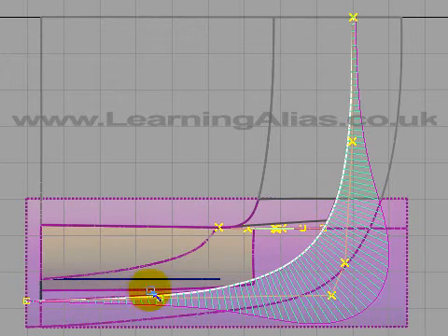And then when you've done that, obviously you have to bear in mind that this must run down the shoulder and be parallel to the side glass. So that's very important. You must set that up. You do that by attaching another curve here, shaping it to be sympathetic to the side glass, and then aligning this curve to that one. When you've done all that, you can project it. I've put the deck here templated in on the screen just to show you how this curve is sympathetic to the line of the deck primary surface. And when you've done all that, you can project it down onto this shoulder surface.